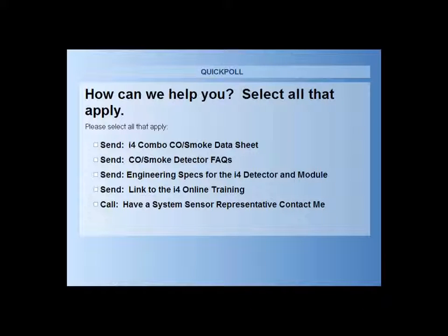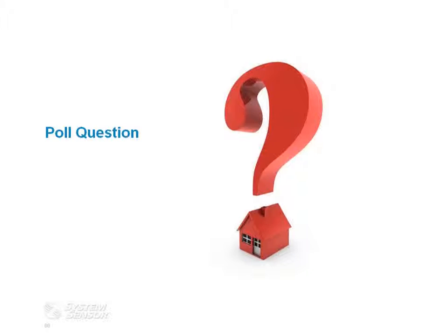What happens in an appliance to cause CO? As alluded to before, carbon monoxide is a byproduct of combustion when a fossil fuel is burned. So anything burning any of the fossil fuels we've listed below, anything from wood to gas, is going to cause that combustion. If an appliance has a leak or a blockage in some area where it can't properly ventilate, that carbon monoxide quite possibly may come back into the home and cause problems.